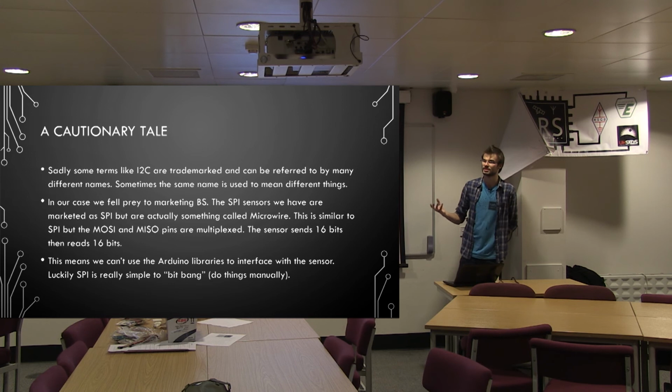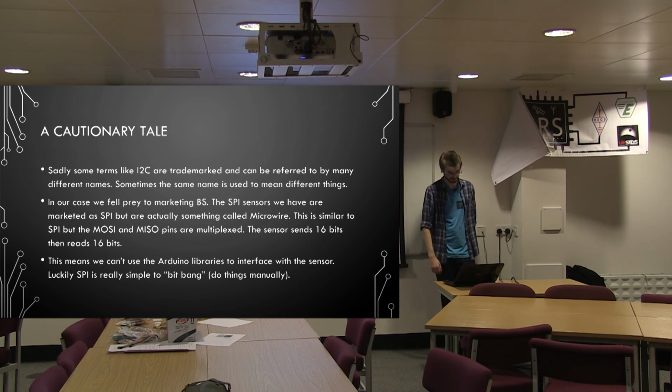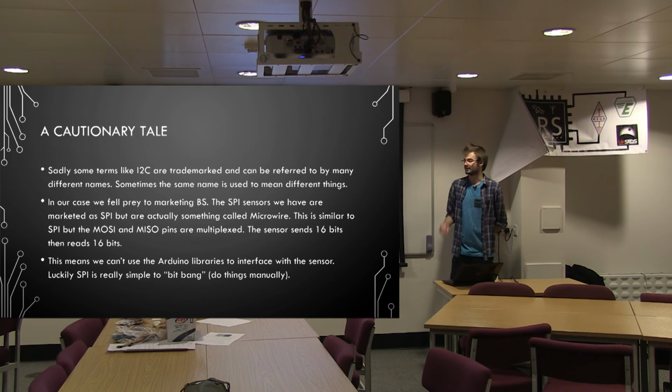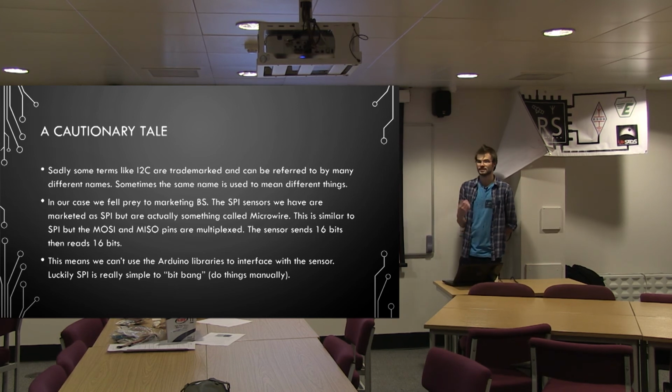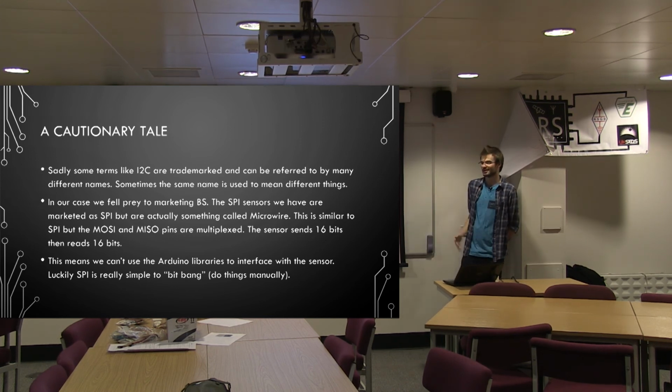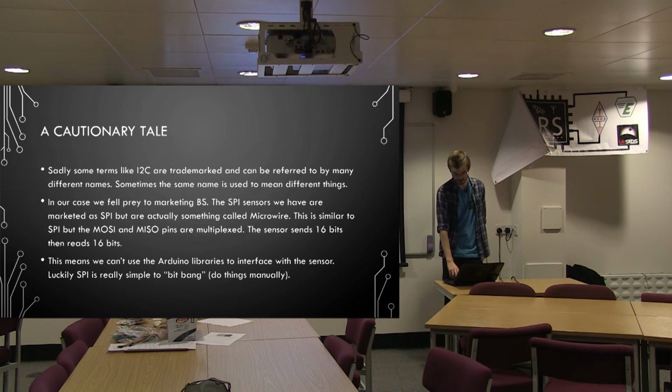That's because the Arduino library is set to interface in a certain way. It's set to do it properly, but some of these devices implement a slightly different way. As it says at the bottom, luckily you can bit bang these, where basically you just cheat, don't use the libraries, and write it from scratch yourself, just toggling the pins up and down. That means you can talk to all these ones that aren't quite the standards and do slightly different stuff.